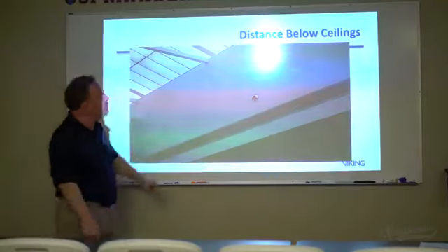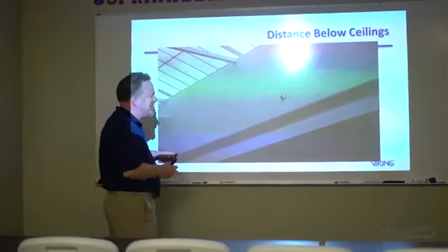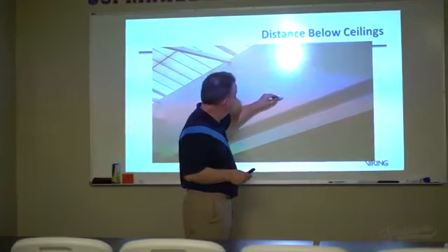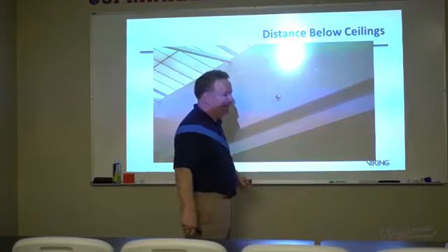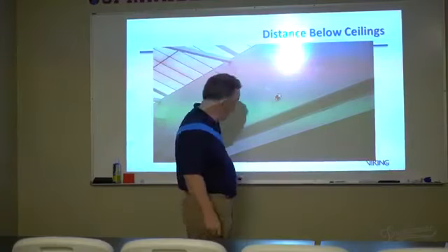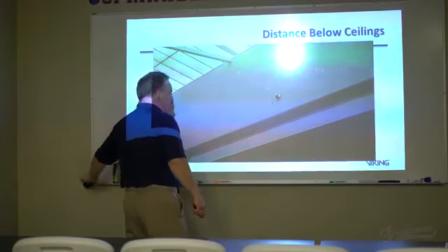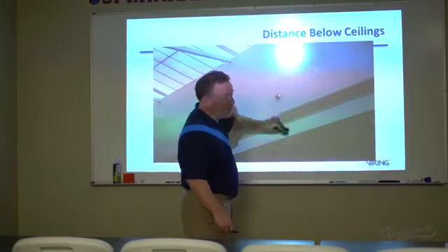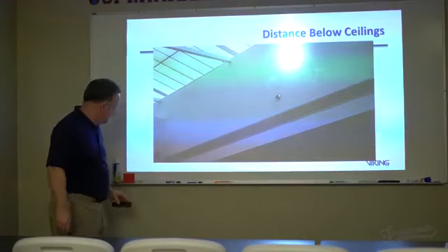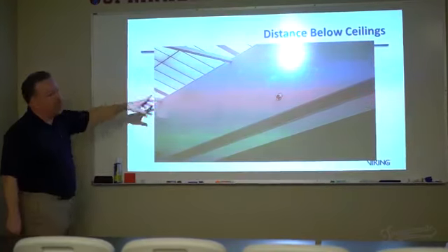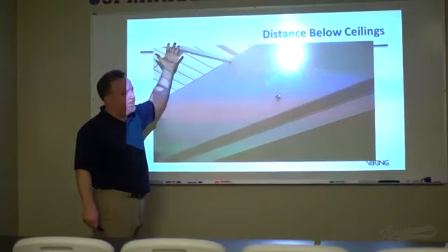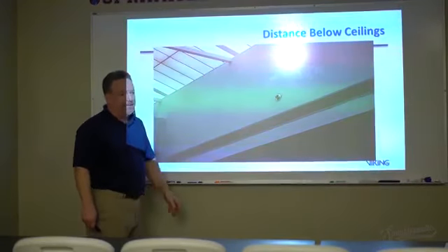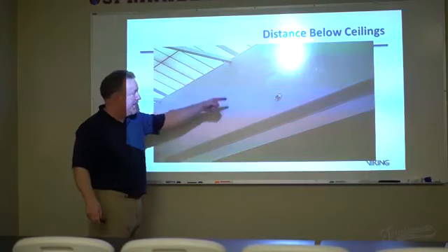Not even if we put a little nun's hood over the top of it to capture heat, which I saw at Pittsburgh International Airport. It's pretty creative, but it's not going to work either. You've got to put the sprinklers up. You can't avoid putting the sprinklers up in the glass skylight area. You're not going to get it with that.